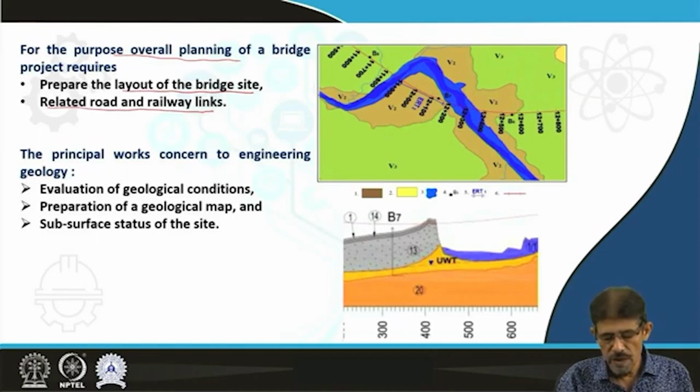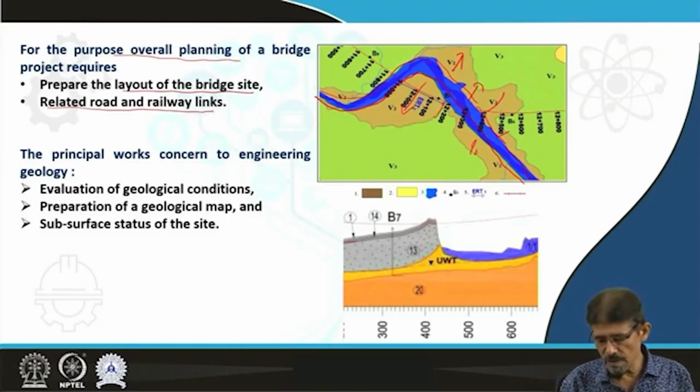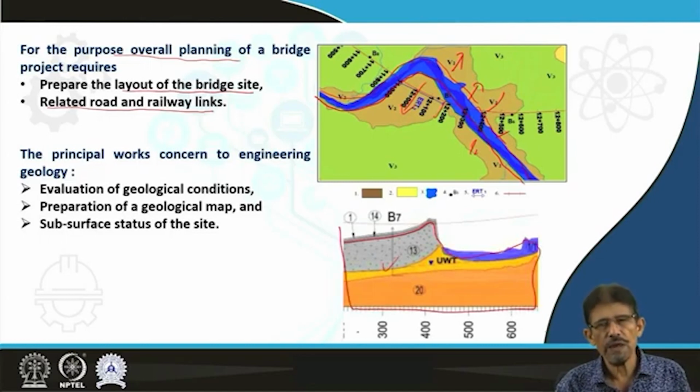You can see the preparation of layout is carried out with the help of survey personnel at different levels to suggest the lithological distribution, the forest cover, soil cover, and different types of problematic zones present in geoground. Then we are going to make some geological sections to show the subsurface condition of strata or soil layers.